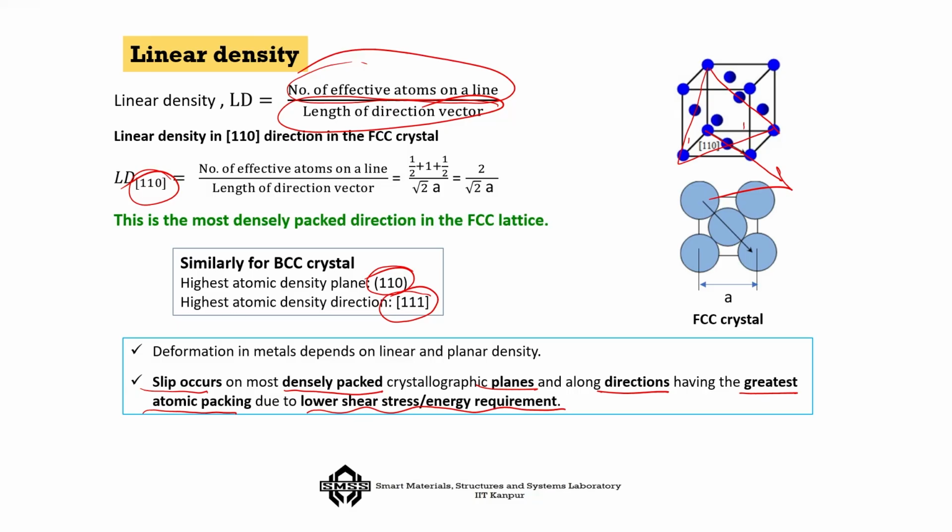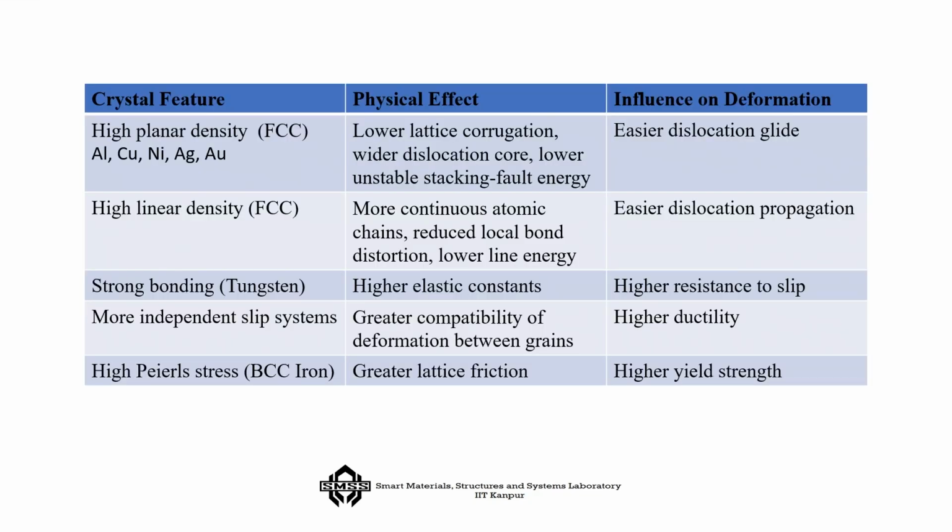Okay? The dislocations or the slips can move very easily across the planes, but for BCC these are not so many, the density is low. So, it is not so easy to move it. So, BCC is more brittle, BCC will give you a less ductile condition. We will see then what materials offer us this advantage.